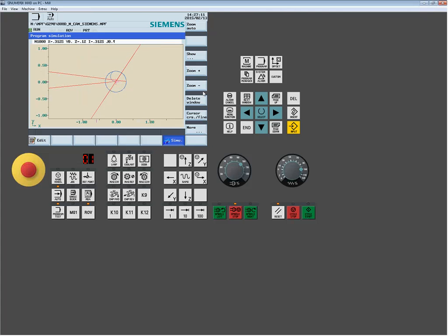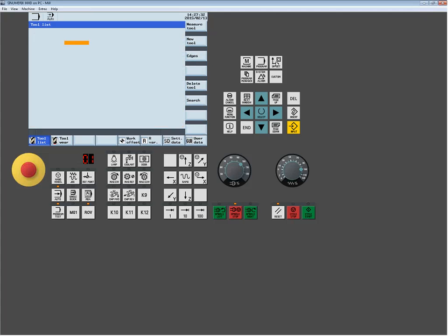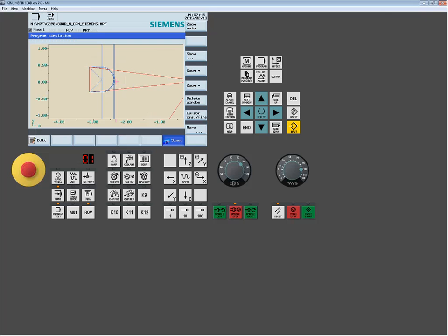Because if they built the placement wrong when they posted it, like, oops, we were off a position, so we put the drill depth of 0.6 right here, one place down, so now it's affecting a reference plane, or maybe I moved it up and all of a sudden my drill depth is under my safety distance field. Those are the things that are going to get mistaken initially when you're first building a post-processor. So use this mask as a quick way to not only modify the program once you're in production and making parts, but to validate that the output code out of the CAM system is good in the first place.